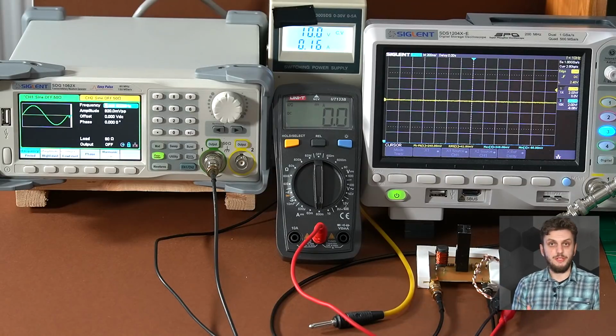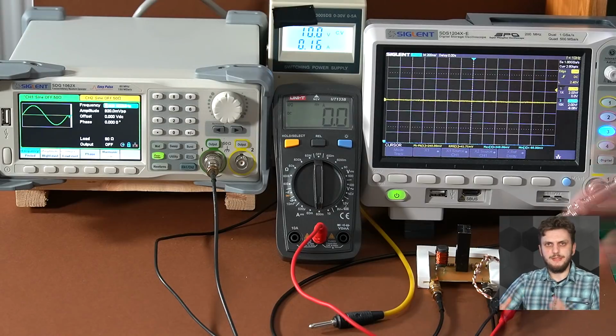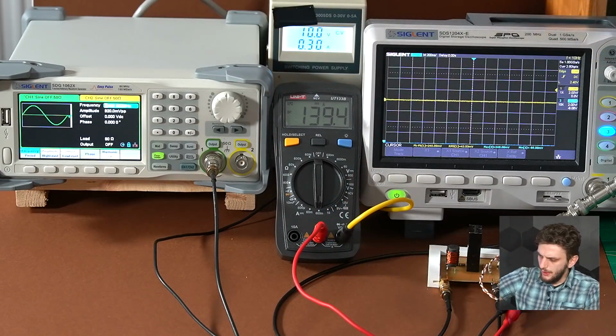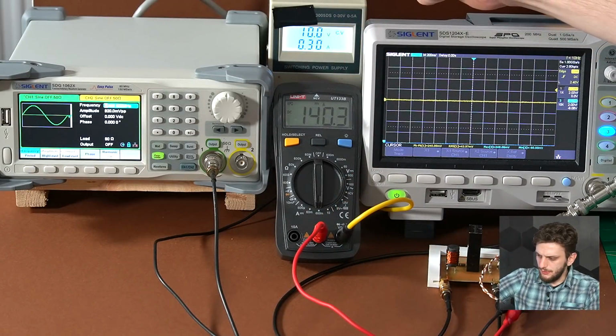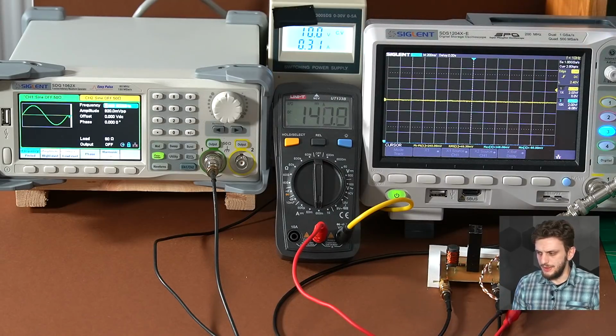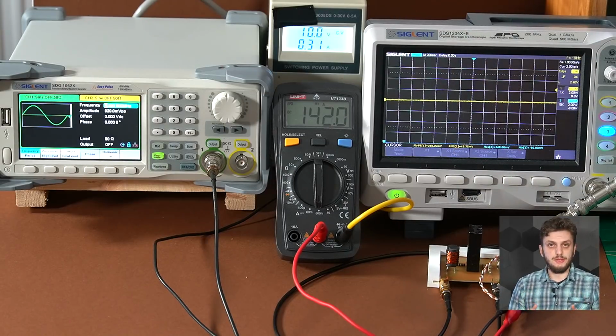So first thing to check out is the current consumption of the circuit. This should be our very first indicator to see whether the circuit is working as expected or not. When I connect the power supply, we are getting about 139 point something milliamps, and we can see that this current is increasing. As the transistor is warming up, we are getting more and more current consumption. This is very close to the total current consumption that the simulator was telling us about.